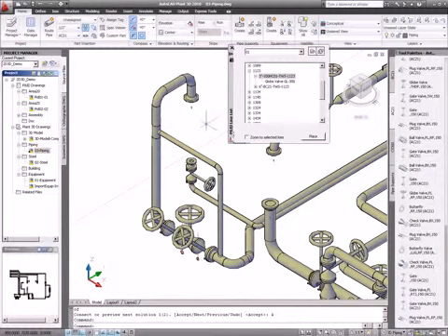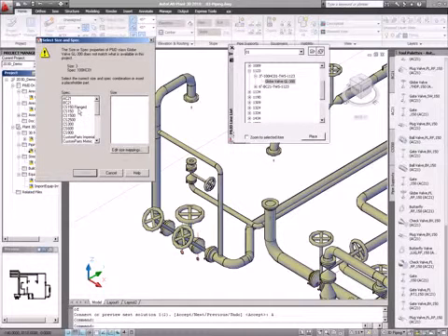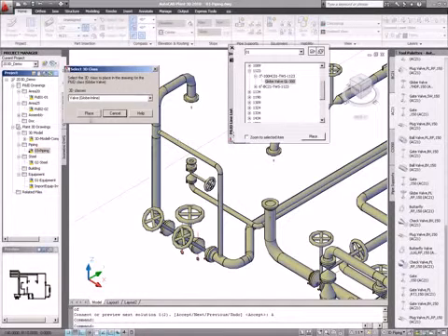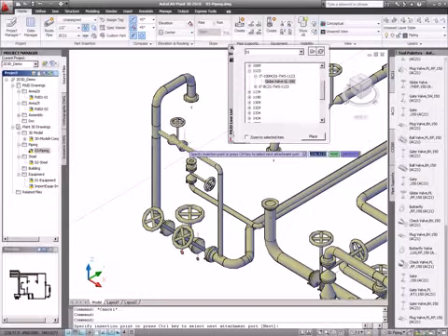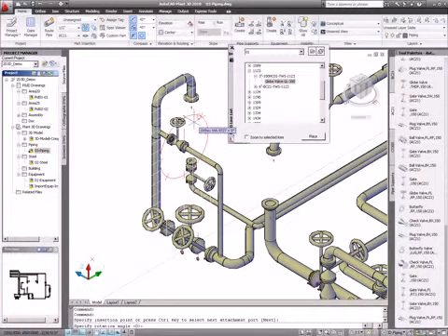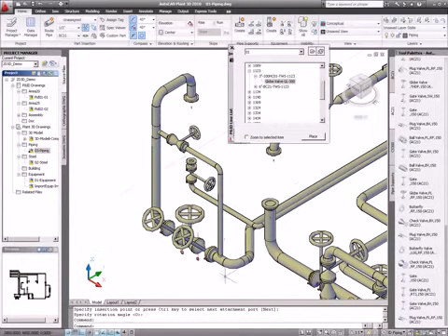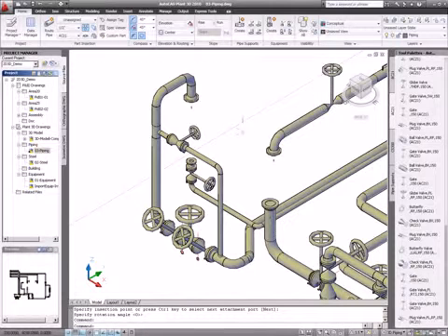The second thing I want to do, add the valve of course. Select the valve, place, and then again, since it says the wrong spec, I select the correct spec and the correct size and place it as an inline valve on the pipe, and that's it. And then give of course rotation for your actuators. Then I can close it. That's the basic with pipe.